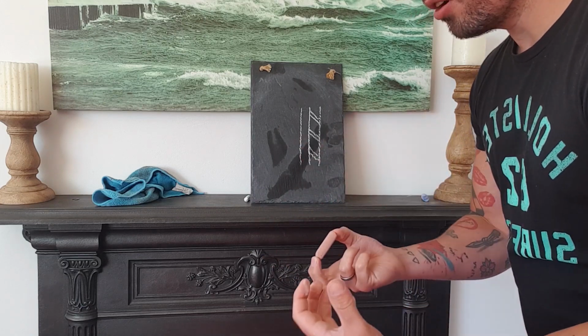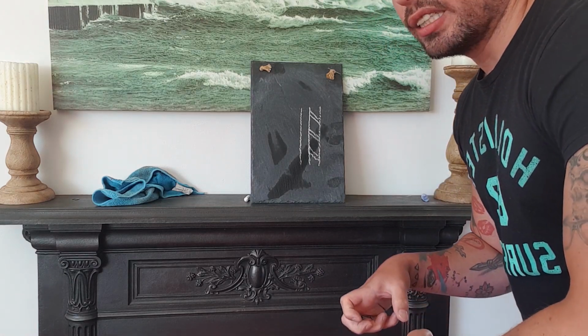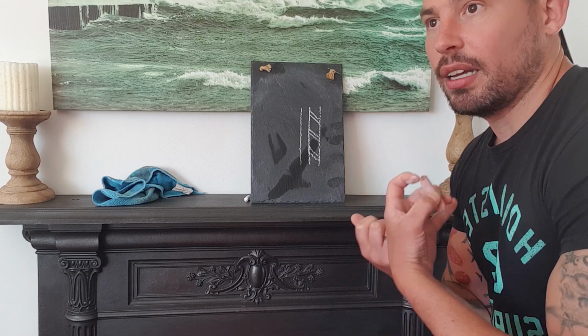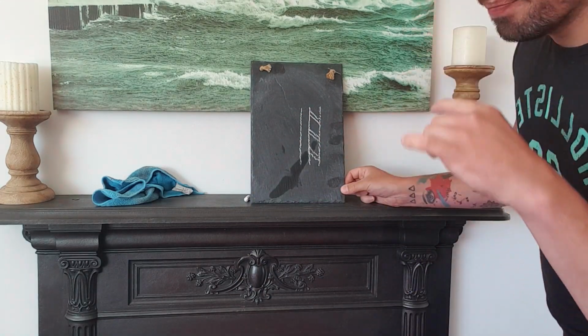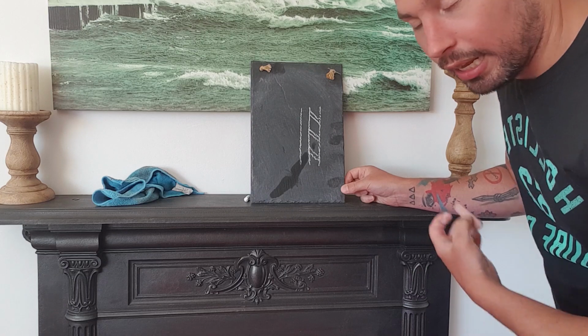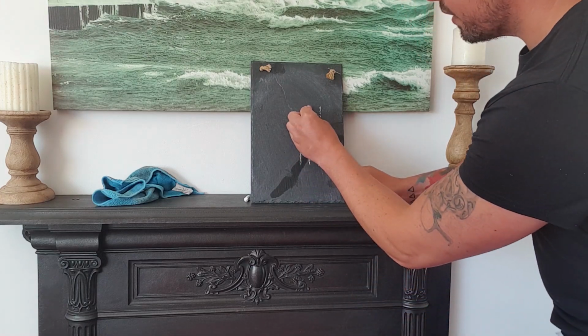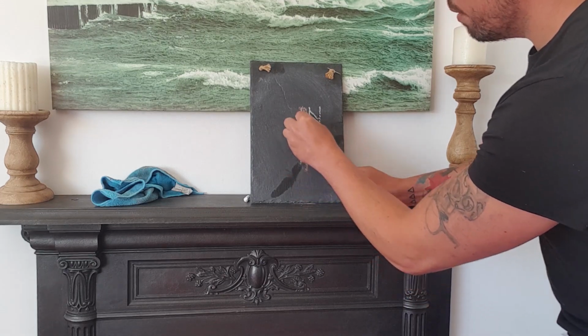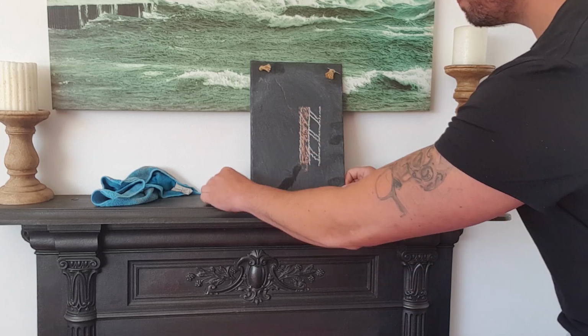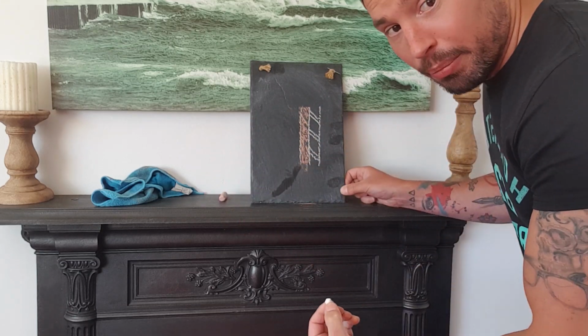We go find products, for example, like Rockwall or Knauf, who will then say, a 75mm insulation will give you this performance. And if that performance matches the criteria and data that the SAP assessors and the acousticians gave us, happy days. So say, for example, a general installation thickness is 75 in a wall to get like a 0.21 U value. So there is our rigid insulation or our mineral insulation, 75. We then have a 50mm clear cavity.